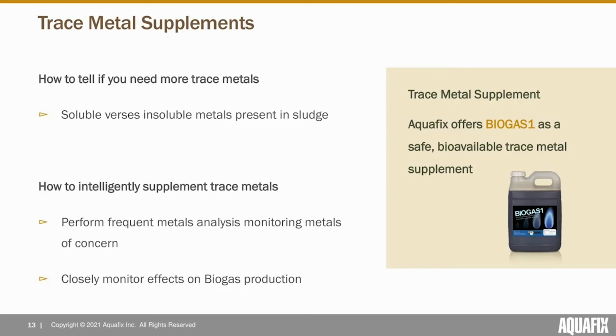All right, we have a couple more questions here. Are there toxic metals we should monitor for? So I'll answer that one first. Yes, there are toxic metals which could be monitored for. Particularly, most of the trace metals can be toxic at relatively low concentrations. So something like nickel or copper, all of them can reach toxic concentrations.